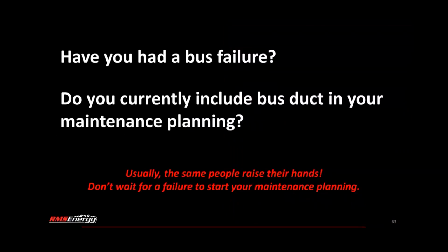The first question, Brian, is can you explain the silver plating process that you talked about in your presentation? Yeah, so there's a couple different processes that can be used, but a general overview of it is to remove the old silver plating that's failing, to try to repair any pitting on those terminations, and then, the way we do it is an electrolytic process where you redeposit silver onto those terminations. It can all be done on site in place, so you don't have to remove any bus duct or cut out those terminations. It can be done where the bus is.